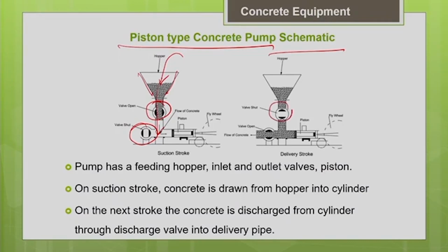Your inlet valve will be closed, and the outlet valve will be open, and the concrete from the cylinder will be forced into, or discharged into, the delivery pipeline. So that is what is happening in the delivery stroke.